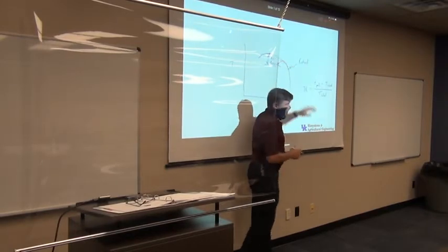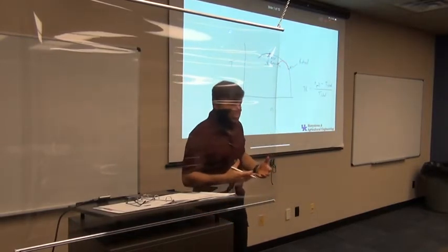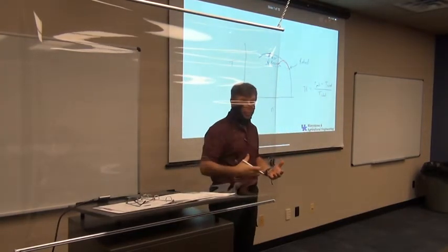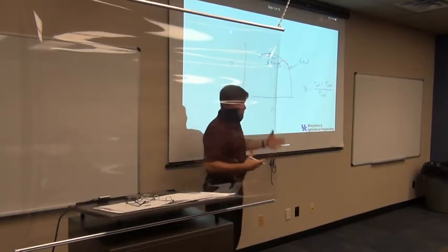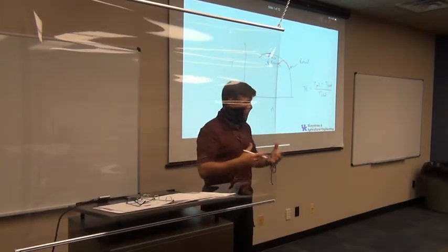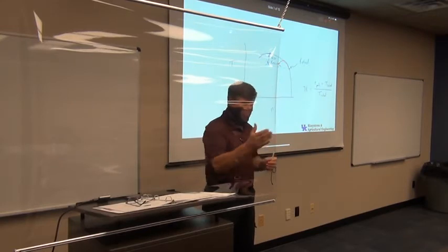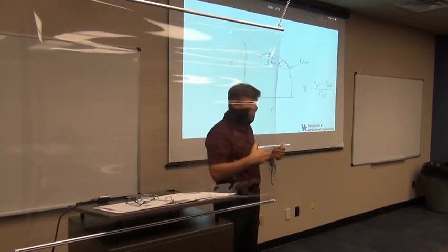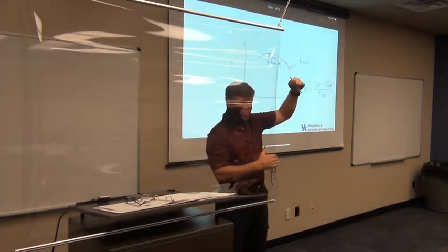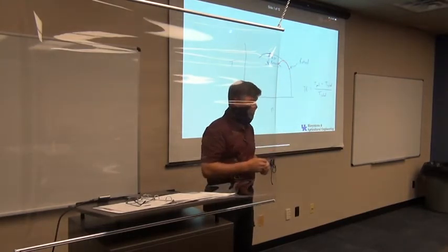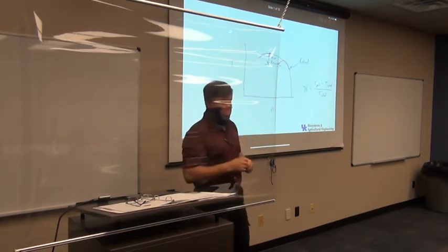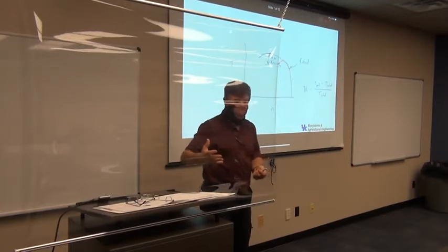The peak is not going to go quite as high, but big heavy engines that we need for agriculture, over-the-road trucks, construction equipment and so on, need that lugging ability. We need that engine to be able to do heavy work, drag things and work hard, and not worry about high engine speeds. So in those kinds of engines you're going to see that longer curve going to the left. You're going to see more rise, more reserve, and that's desirable for that kind of performance. So you'll see a lot of different shapes of curves with different engines, depending on the application, depending on what you need it to do.